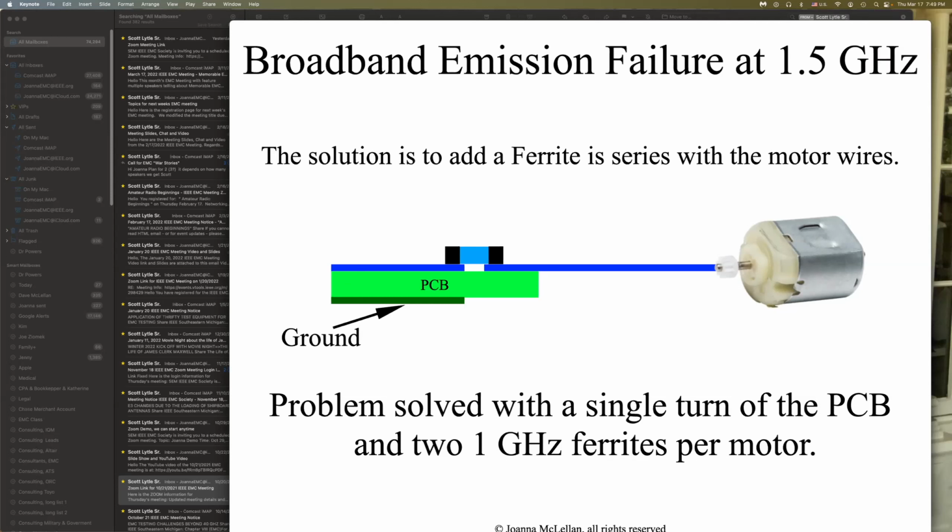Yeah, think of it as an oscillator of sorts. An oscillator works by just basically electrical noise, which is very broadband in nature, and that's what actually gets the oscillations going. Same thing with the brush. The oscillator or the resonant circuit here happens to be based on the dimensions, making it an antenna. Yeah, because it's a quarter wavelength, I'm not sure if a shield would work on the wires. That probably wouldn't be a good plan.